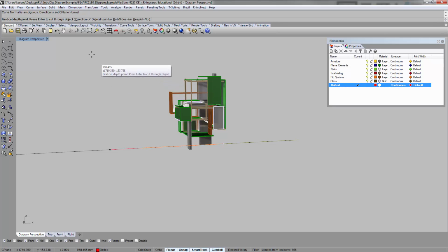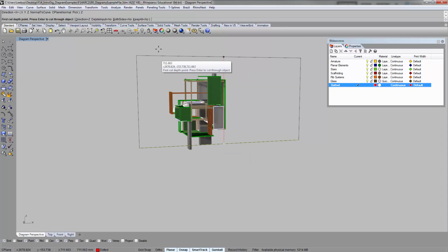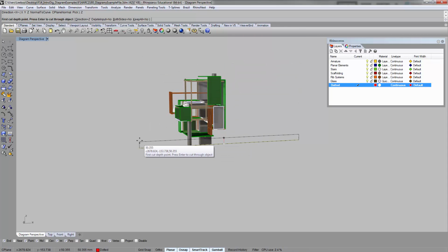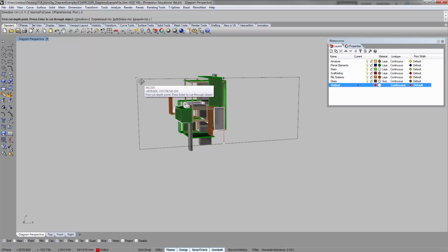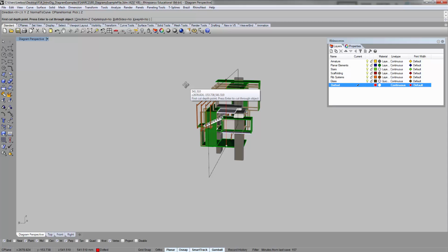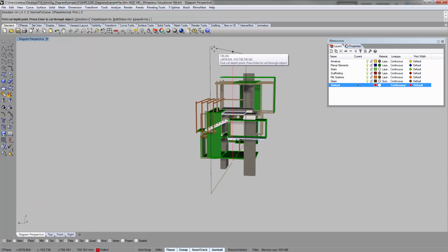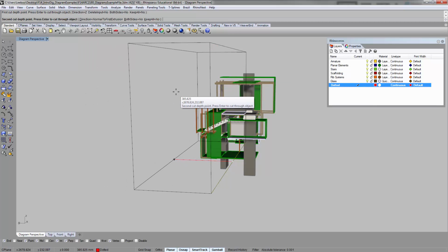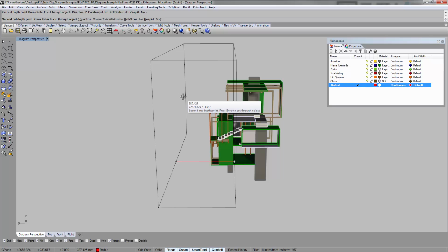And it'll actually say direction. By default, it should actually be Z, so it should show you something like this, all right? But those were just some added options I was messing with earlier. What this does is basically ask you for the plane of your cut. So you just make sure you drag it above the top of your model, and click anywhere, and then it'll move into this, which is the direction of the cut.